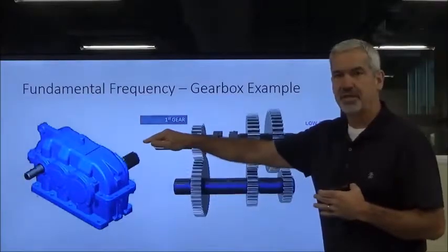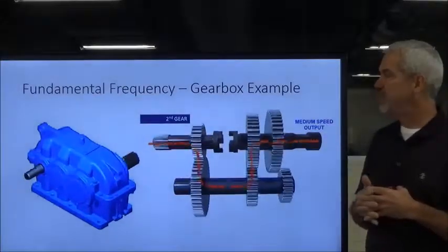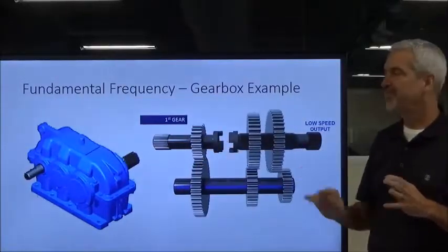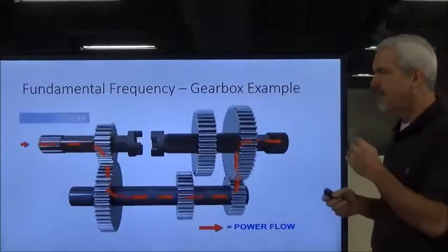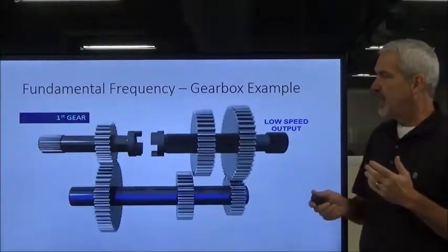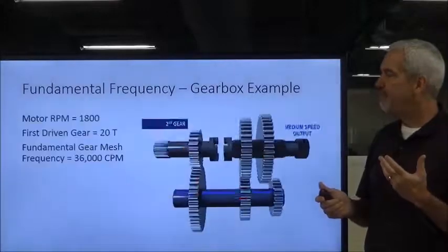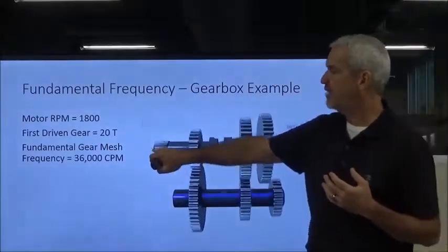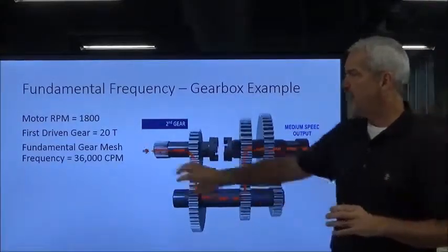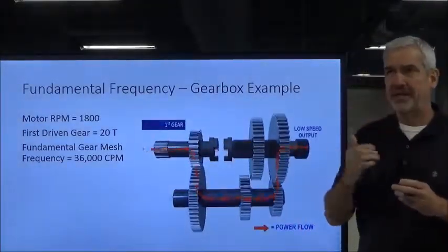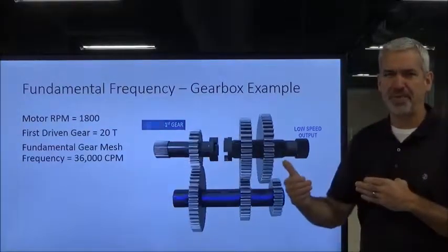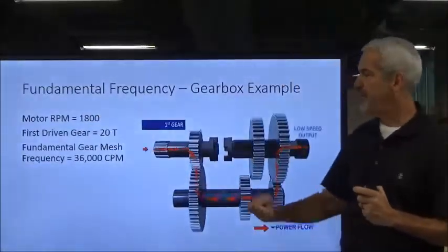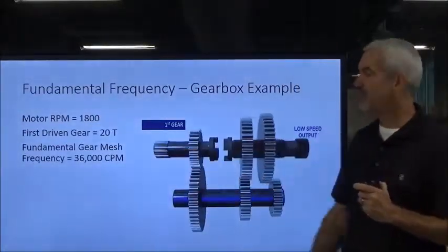That's all derived from our input shaft gear, that very first gear, and that gives us our predominant frequency. Now, let's go a little bit further with this. Our predominant frequency is derived by a simple formula. We take the motor RPM, or that driven shaft RPM. You typically don't couple a gear and a motor together through a belt or anything like that. It's a direct couple.